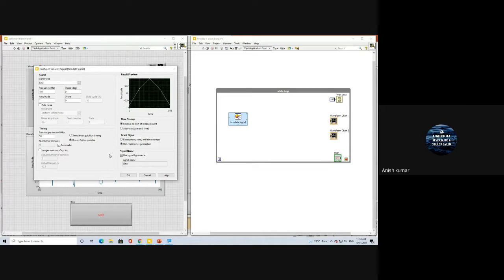so we'll get a signal like this. Again, this is not an accurate signal. So this is due to undersampling. We call this undersampling the aliasing effect. Hope you might have heard about this, right? So we call this the aliasing effect. This is not reconstructing the original signal, right?